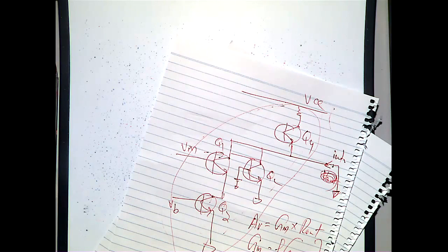When should we add channel length modulation, 1 plus lambda VDS, when calculating the ID? Because for most of the quiz questions, yeah, we haven't taken lambda into account. I know what you meant. The equation needs 1 plus lambda times VDS, but we don't know the VDS. Yes, so we need to use VGS to represent that. Because we don't know the VDS, we haven't taken the 1 plus lambda VDS term into account in the quiz. Maybe that is the question you are asking? Yes, like for question 7, you added it. You used VDS.